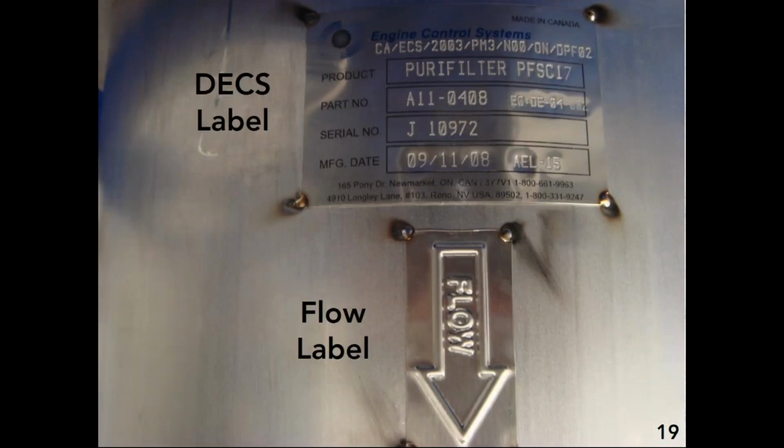Here's an example of a pure filter device and the family name at the very top, CAECS 2003 PM3 N00 ON DPF02. So it was verified in California. The company was Emission Control Systems. It was verified in 2003. It's a PM level 3 filter, so that's the highest level there is. This particular filter has no NOx reduction associated with it. It was certified to an on-road standard, so it should only be installed on on-road engines, and their number is DPF02.